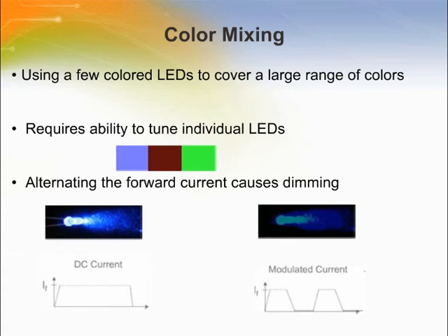The lower the duty cycle, the more dim an LED appears to be. Another way to think of it is when an LED is on full brightness, there is a DC current flowing through the diode. However, if the LED is half on, that means the forward current is operating at a 50% duty cycle. So even though there are many benefits for using high brightness LEDs and signs, there are a few design challenges that must be overcome.